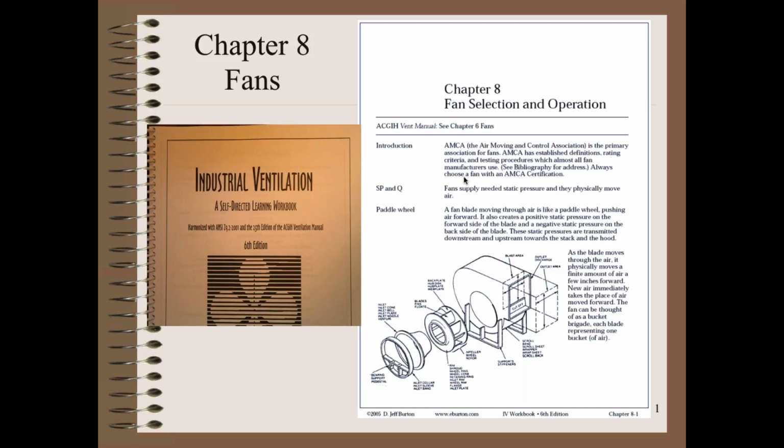Well, we know the velocity pressure is basically determined by how fast the air is moving. What's the static pressure out here? Zero. It's atmosphere. There's no static pressure. As soon as you leave that fan housing, the static pressure is zero. The velocity, you feel the force of the air, right? Because that's velocity pressure, but there's no static pressure. Nothing for it to push against, right? So that static pressure is zero.